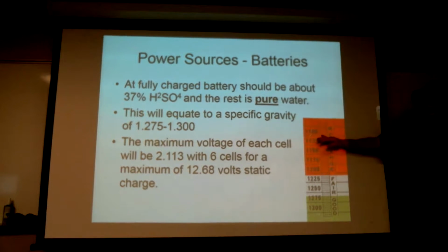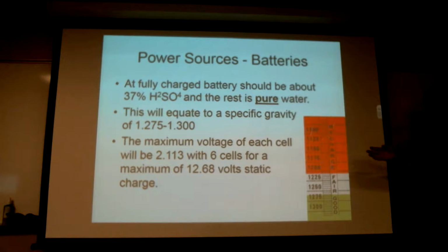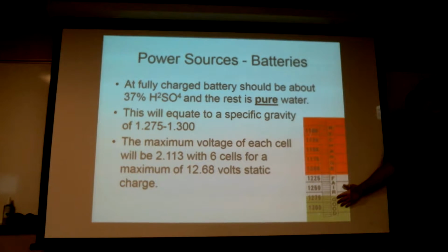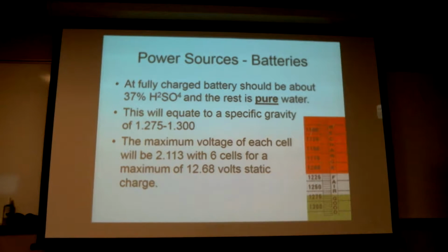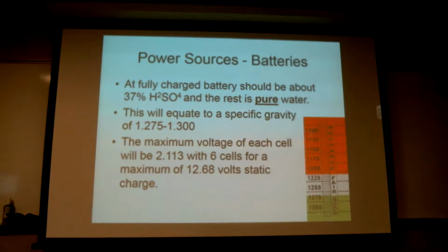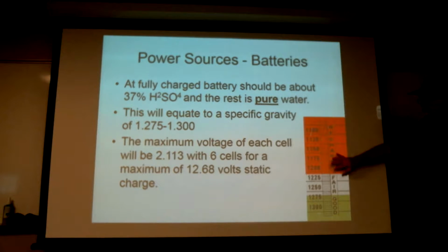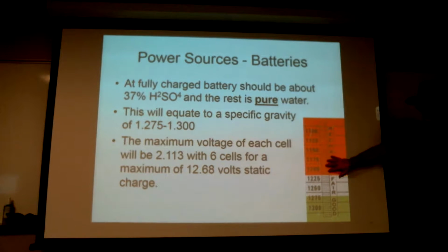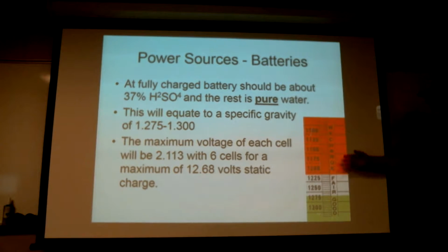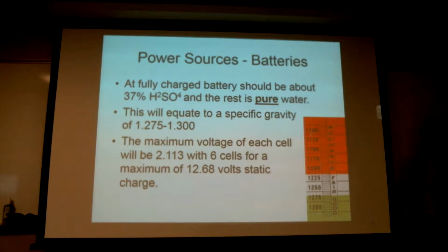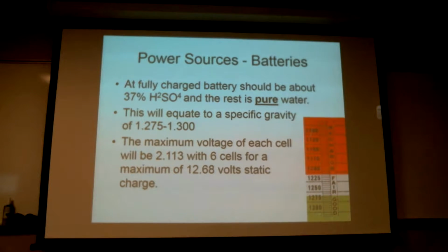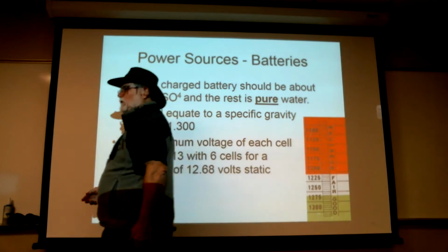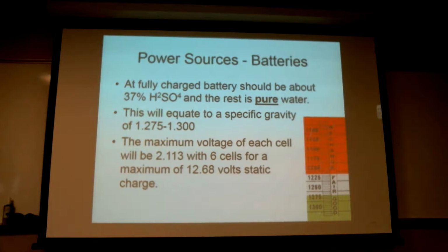If it isn't, the first thing I got to do is recharge the battery. I can't do anything else. Got to get the power source back up to snuff. Once I've got the power source back up to snuff, then I can start the engine, do other things, and start doing other diagnosis. That's why oftentimes these guys, they'll just have a red, a white. Some of them are so simple, they don't even do that. They just have a series of little balls. If all the balls are floating, it's charged. If half the balls are floating, you need to recharge it, half or less. So some of them are pretty rudimentary and simple.